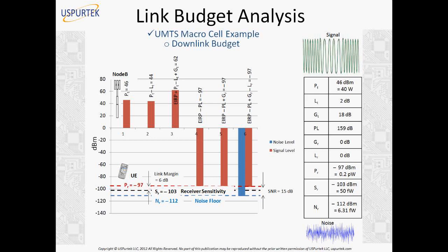We have to calculate what the received signal power will be at the edge of the cell, so that we can define our boundaries for the cell. Now 8 kilometers is okay, but if our signal level is not right, then we may have to reduce the cell size, or if we have plenty of signal, we may add to the range of the cell, right? It may be more of a business decision at that point, how much investment we can put into cell towers, how many more cells we can deploy, and what the revenue from the users will be. So here we may have to make some adjustments.